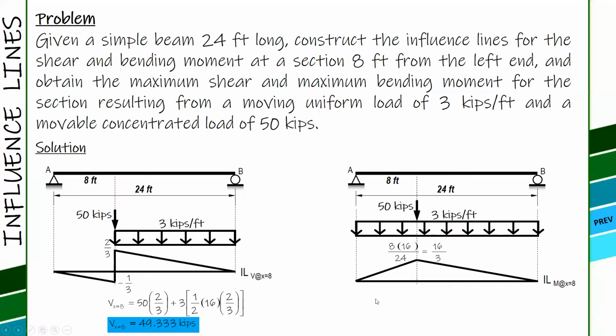And then compute. Moment at 8: magnitude of the concentrated force times ordinate, plus intensity of the uniform load times area. 1/2 of base 24 times altitude 16 over 3. That is the answer.